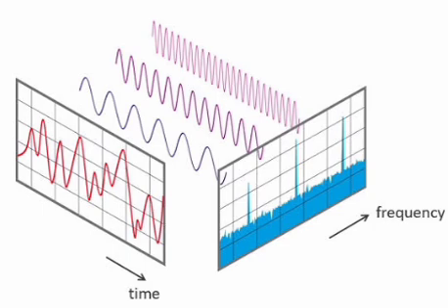FIR filters are often preferred in many applications. They provide an exact linear phase over the whole frequency range, and they are always BIBO stable, independent of the filter coefficients. Two simple realization methods for FIR filters are direct form and cascade form.